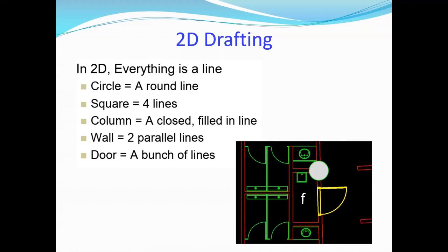We can automate fabrication. I'm not sure about Sri Lanka, but in Singapore it's very common. We do it in BIM, then for steel elements, the CNC machine can cut based on the BIM model. We don't need any additional process. The CNC machine can cut the holes, the sizes, everything based on the BIM model. So that's the advantage of BIM.